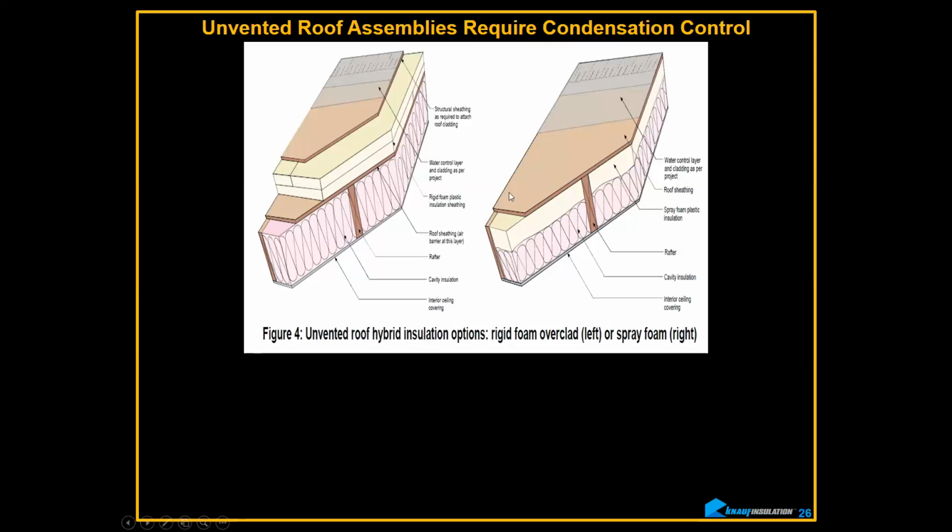And then on top of that, you put a peel and stick layer, and that wants to be permeable if you're using this exterior insulation. If it's here, it wants to be impermeable. Water control layer right there. So that's really the way you do it. And you do it this way in all climate zones.